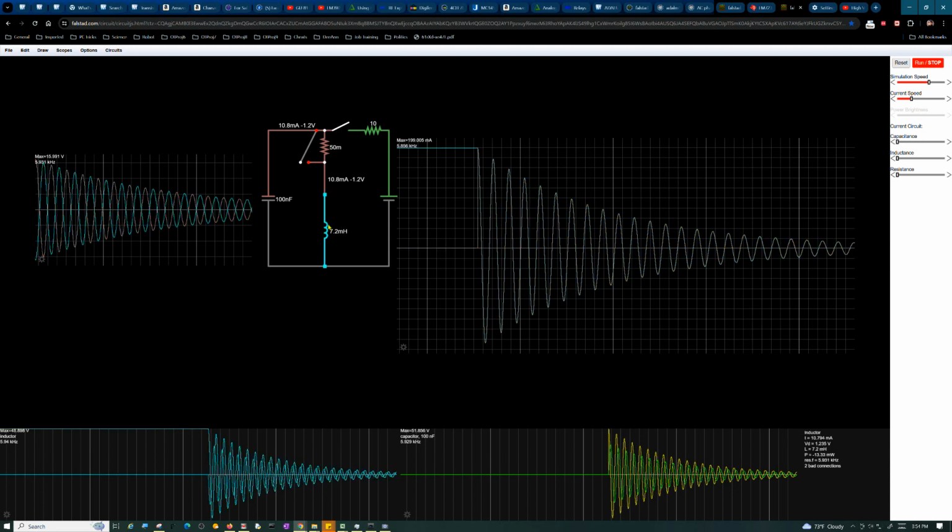But again, this core isn't a high loss core like what I'm using here. But again, we're not far from that, and the frequency is 5.9 kilohertz or so. My frequency is 4.8 kilohertz, but again, it's a lossy core. I'm surprised it oscillates at all, because it's eating energy not just with every oscillation, but every time it changes, and it's a lossy core. You've got eddy currents and all that in there absorbing it.